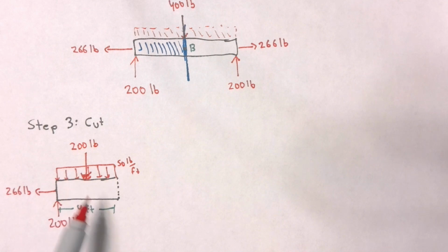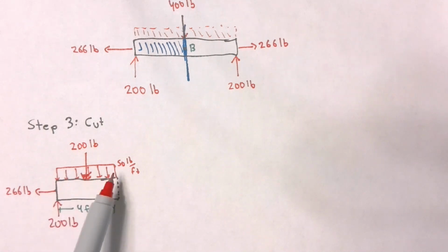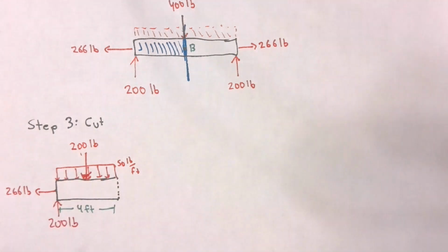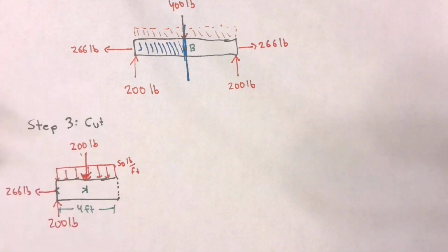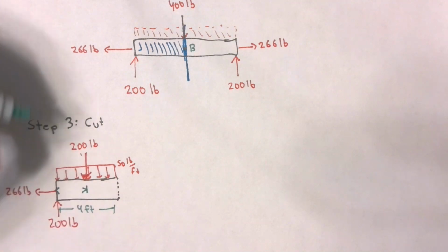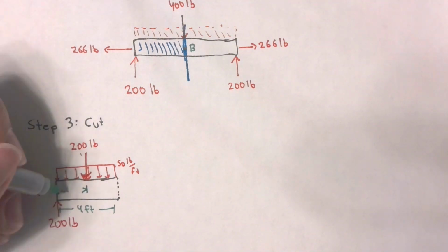And again, this is half of the beam, and this is a rectangular load, so the actual force should be equal to half of the force, which 200 makes sense. This is a rectangular distribution, a rectangular load, so what's the distance from the left to where that 200 pounds are acting on? 2 feet. Yep, that's correct.